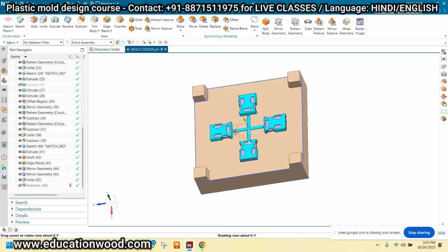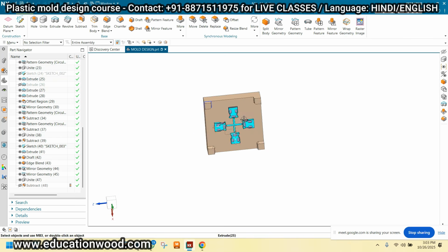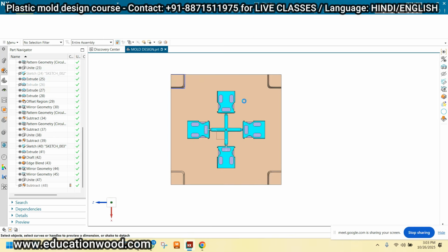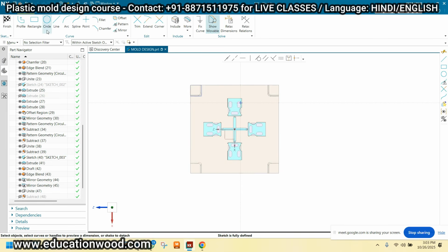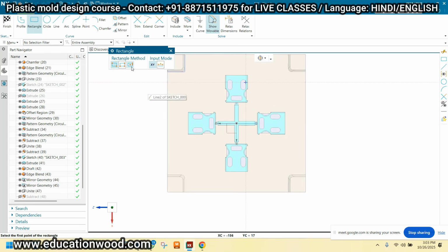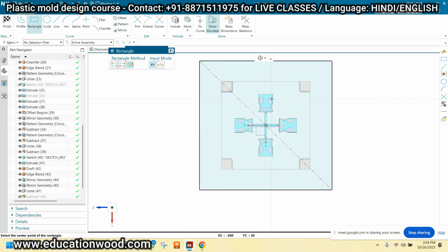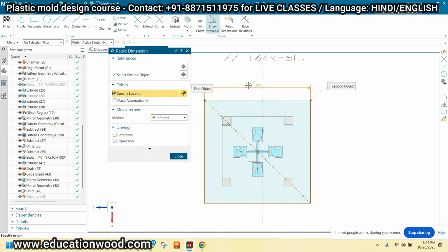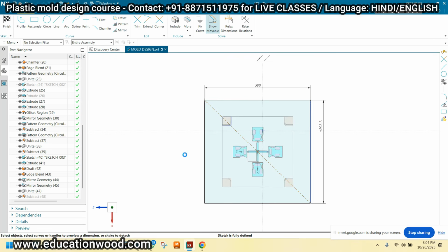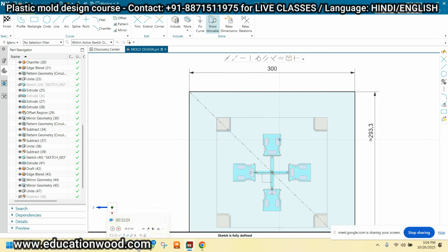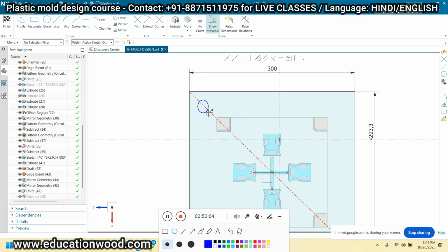Now try to understand. Now I will make the housing. Just click on this, and I will prepare the housing. So take the center. Now tell me what is the size available in the market again. Basically, I have to use some features here. What is this? Guide pillar and guide bush I have to use, right? One more thing is the return pin I have to use here.